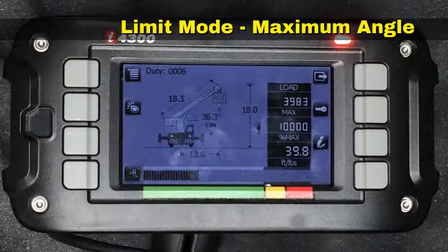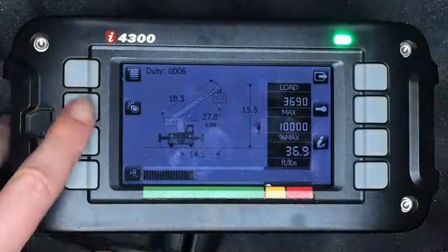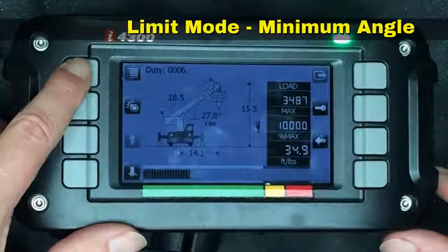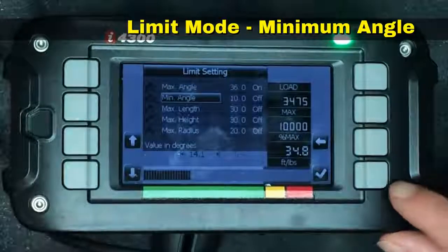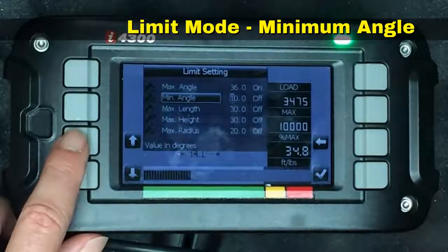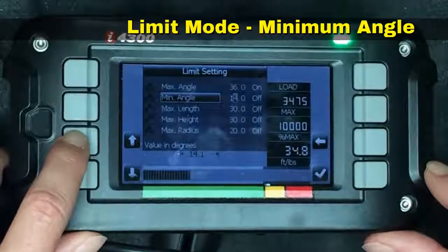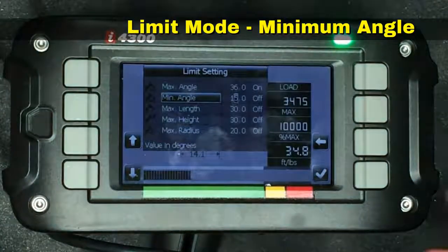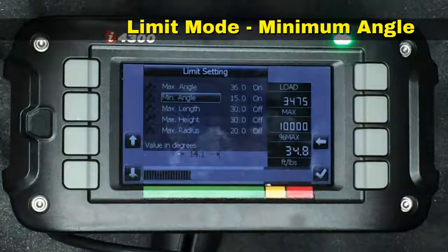Now we'll go ahead and take a look at a low angle limit indication. In order to do that, we'll come back in to the mode button, go into limit mode, select minimum angle, and I hit the check mark. So now I can actually change the setting digitally. So let's say I want a 15-degree minimum angle. Hit the check mark again, and now it's turned on.